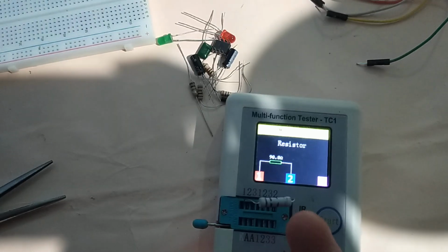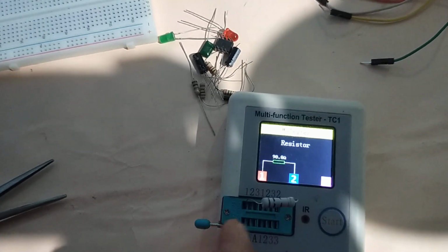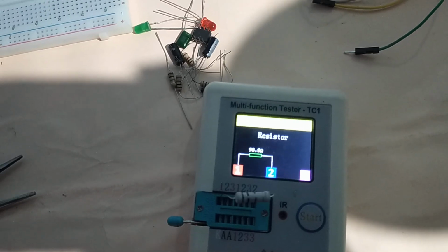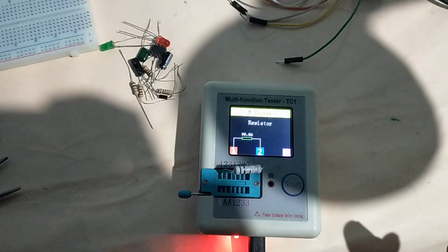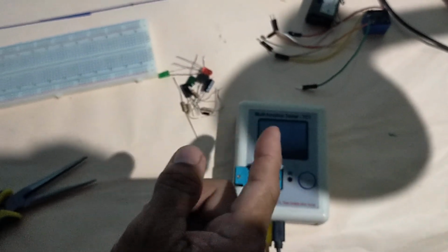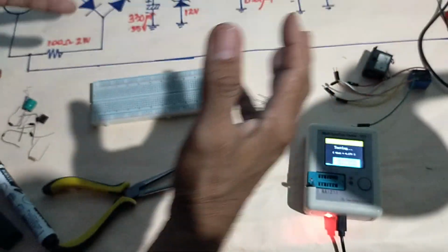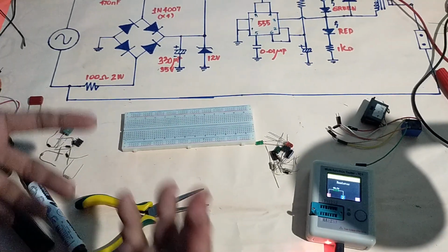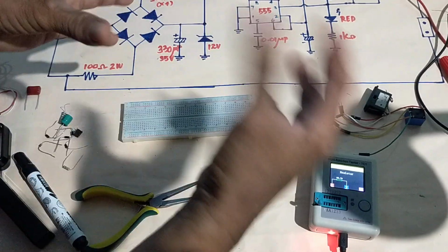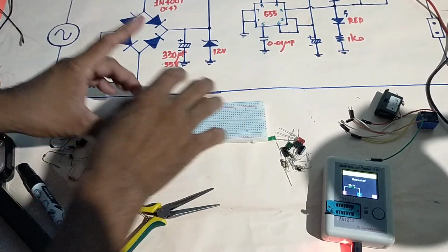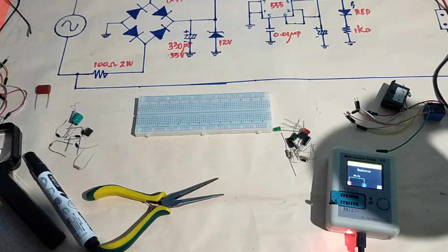But when we read the resistance based from their color codes, brown, black, brown, that is 100 ohms. But there is a tolerance given here which is gold. That is more or less. So there is usually a deviation of resistance because of the tolerance. But based from this tolerance, 98.8 ohms is still good. Okay. So after the components are measured, we'll now proceed to the assembling. We will make sure that all the components that you are going to assemble on the breadboard are still good and functional. Okay?